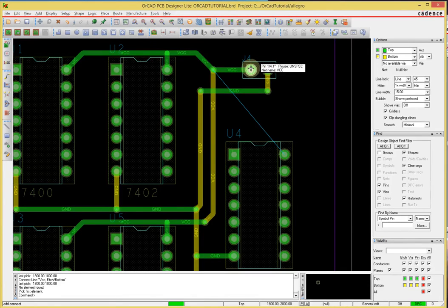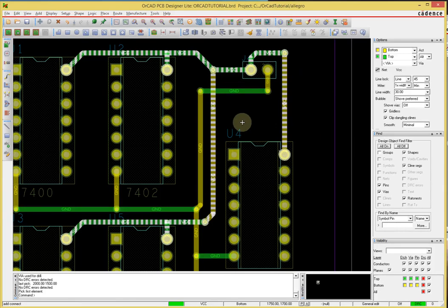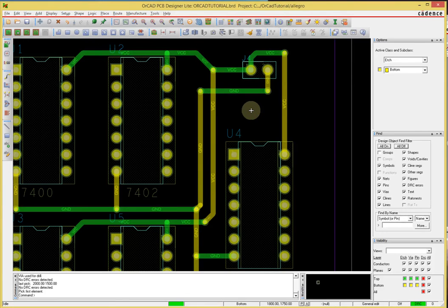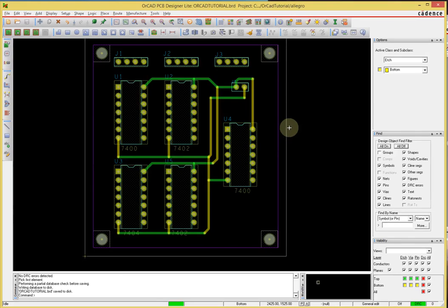and I'm going to again violate my rule because I'm going to make very small motions. I'll come back here around there, and then double click to insert a via, and then we make it straight down here. That looks a little bit more presentable than what I had. Okay, done. Control S, yes. Alright, my power traces are in place. Now I can go ahead and start adding traces for the signals.